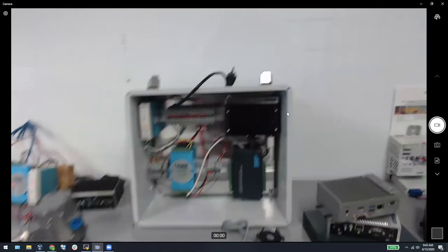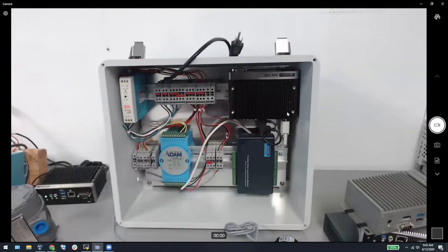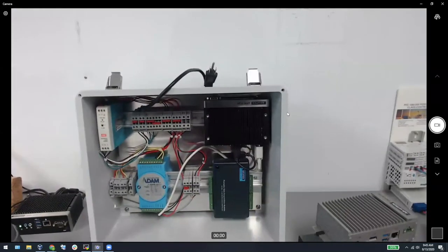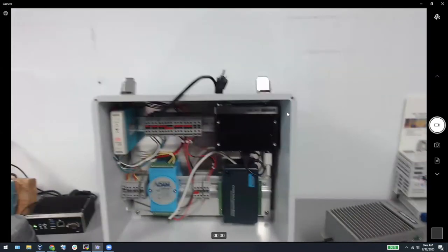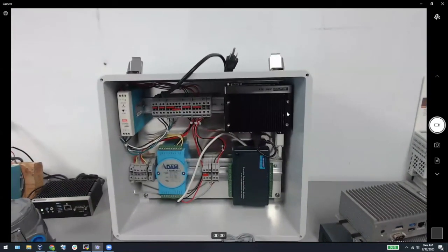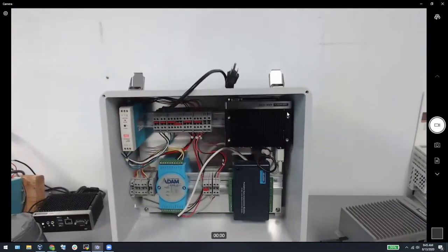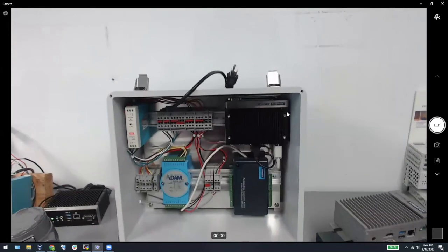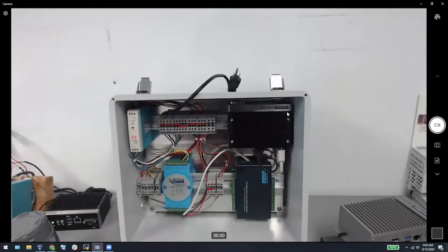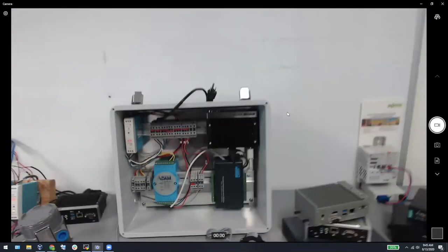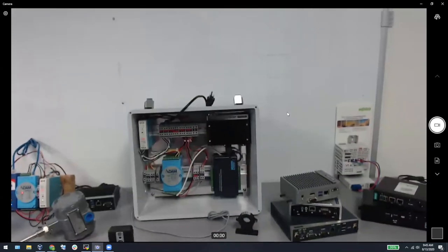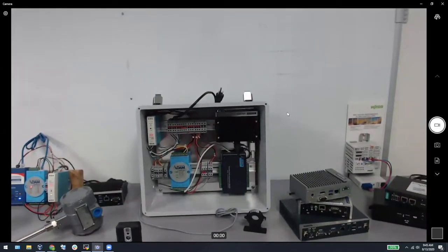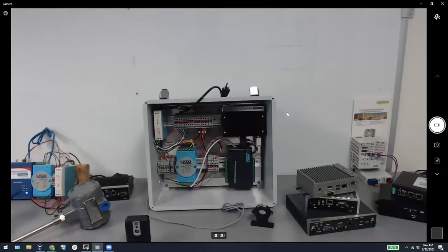And so here is a typical panel setup that you may see. It would include a gateway on the top left or top right, perhaps a high frequency data acquisition module seen on the bottom right, or perhaps just a simple data acquisition module seen on the bottom left, as well as a power supply, all on DIN rails within a panel that you would typically see, waterproof and sealed tight with conduit.